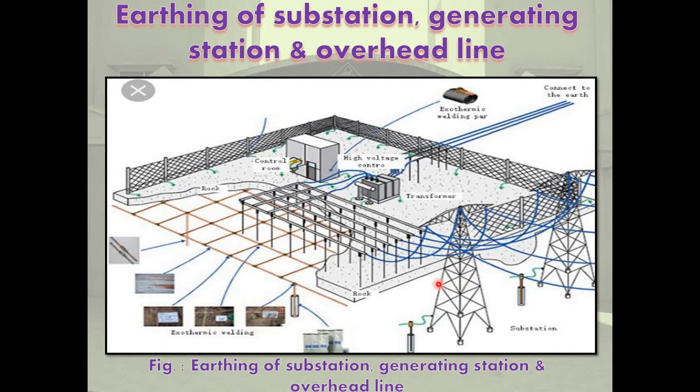Induced lightning surges are produced by a passing charged cloud by induction effect in the transmission and distribution line. Induced lightning surges have less severity than direct strokes. However, they can cause flashover in distribution lines as the clearances in distribution lines are low.